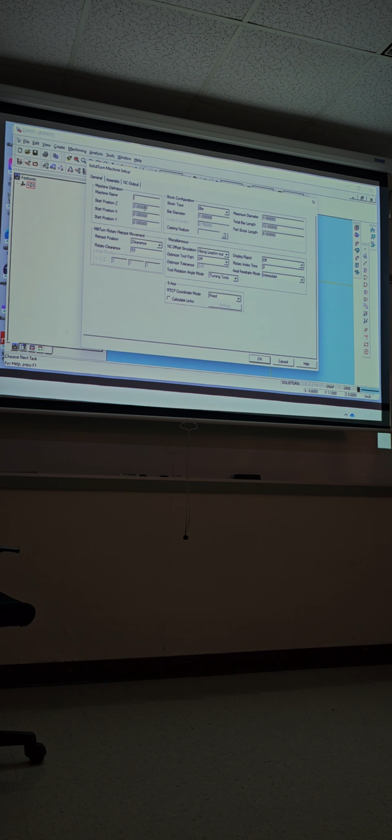After the geometry, we're going to go ahead and switch to solid turn. So we have to make the stock. We're going to go to machining, machine setup. How much are we going to face off? 0.100. This is bar diameter, 3.1. Maximum diameter, 3.1. Total bar length, what is it? How much are we facing? 0.100. So it's going to be 7.1. Very good. Bar stock, 7.1.